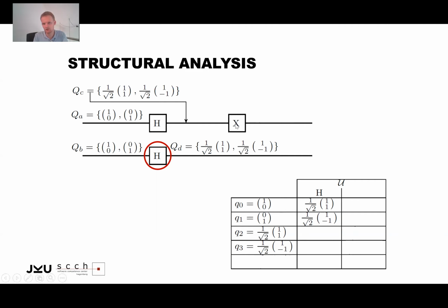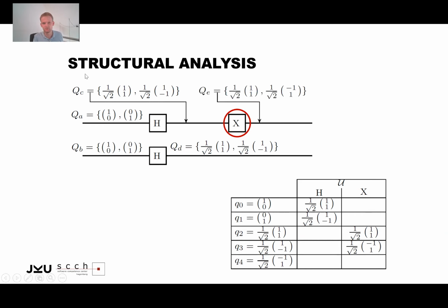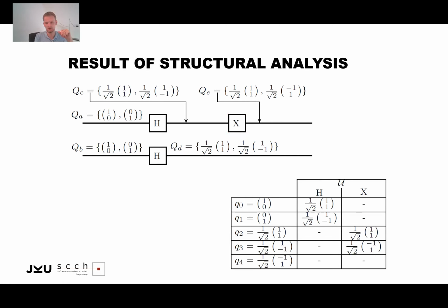Now, if I consider this X gate, I can conclude that this X gate might be applied to states described by this one here. That means this X gate now has to be considered for this state and for this state. So I can make the corresponding calculations. And by this, I can derive that I now may need another state, namely this one here. This state here has already been considered. So this table now shows all the potential states I need to represent, namely all those 5 states which this circuit may assume, and all possible state transitions which need to be encoded. And with this, I get a combinatorial description of all possible states and all possible operations. And now technically, using this table, I could derive a multi-valued sub-encoding, which describes all those possible states and transitions.